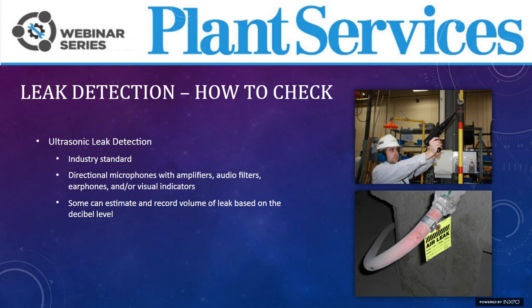Many compressor vendors offer this service, or you can rent the equipment. The first time you're doing a leak audit, I'd recommend hiring an experienced professional to do the leak audit for you, and then really watch and learn and determine if that's something your facility wants to do on their own.